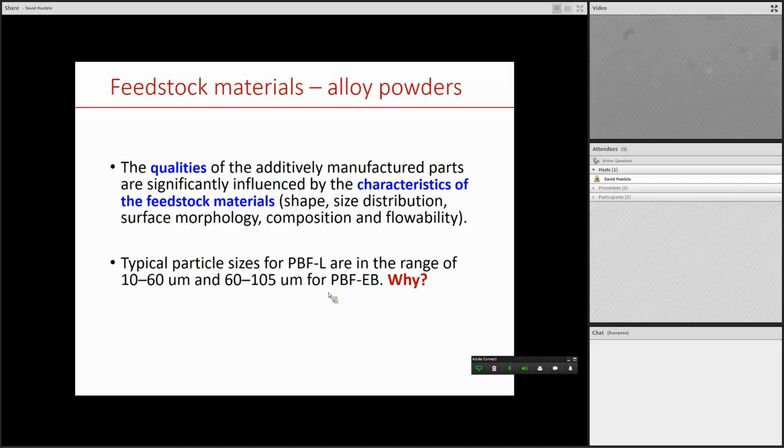Part of what they do in E-beam is heat everything up to slightly sinter it, turning the powder into very loosely connected powder. My impression is that if the particles are too small, it's going to transition from powder into a fused block too quickly, so they have to go slightly larger. That's my understanding of it, but the heat source is very different.